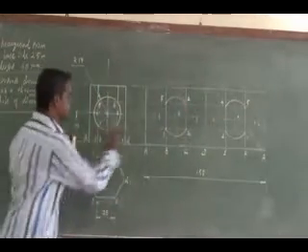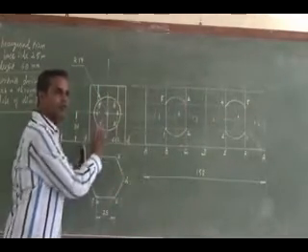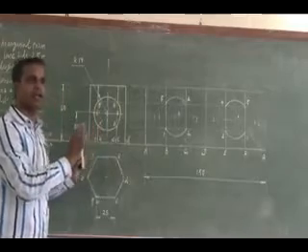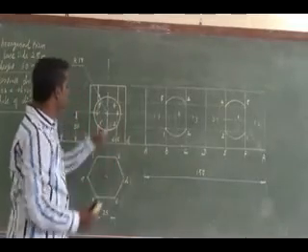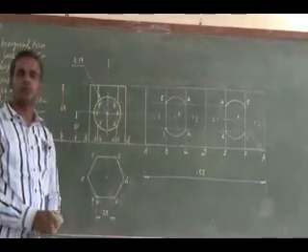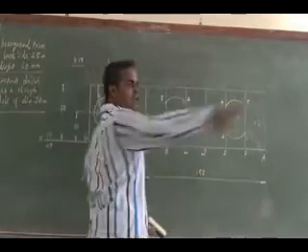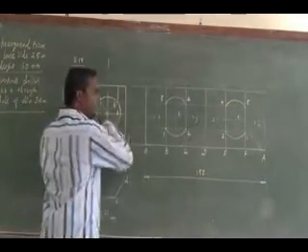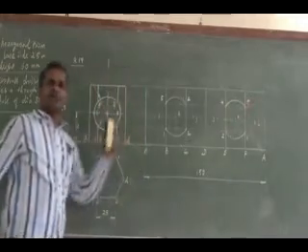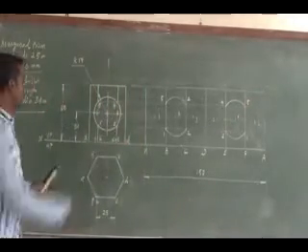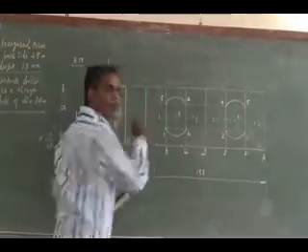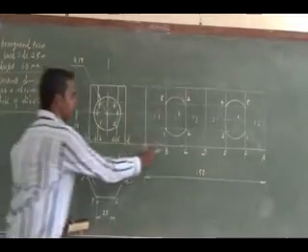So it is on a slant face in my front view. It is not a parallel face, right? It is an inclined face in my front view. So how can I mark that? It is exactly on the central line, that I know. 6 and 3 are on the central projector, exactly on the central projector you have drawn. But what is the exact location? I have to mark it on this face AB.